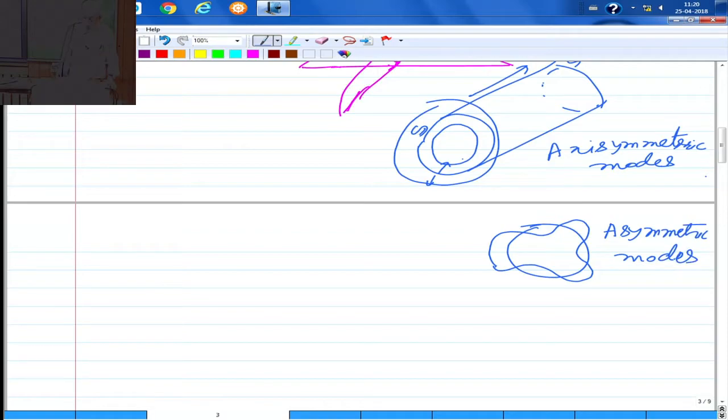And again these can be symmetric or antisymmetric with respect to the axial symmetry line, that is the center line, if the boundary conditions are identical on both sides. Even here, if you want to theoretically find the natural frequency, if I start from here, this is one full sine wave, this is another full sine wave, and this is the third full sine wave.